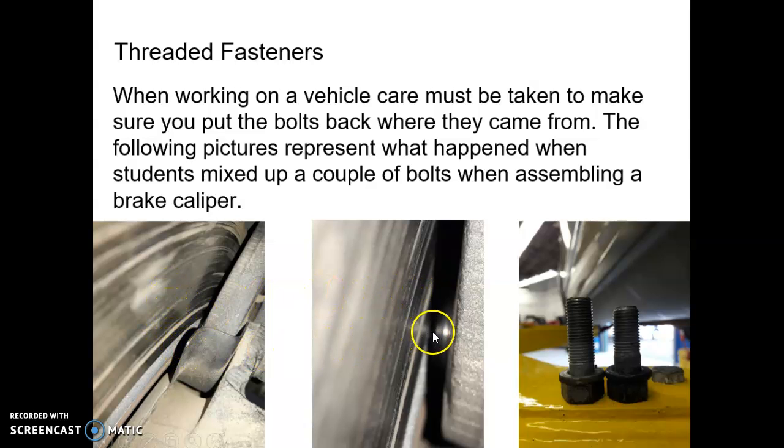The bolt was against the brake rotor and actually froze the wheel until we applied enough gas. It started to move, and it actually rubbed the bolt against the brake rotor enough to wear the brake rotor and the bolt. So it becomes very critical. A little difference in hardware can make a big difference in what happens after you service a vehicle. So you need to be careful and make sure that the right bolts go back exactly where you took them. This is one of the beginning technicians' biggest failures, not paying attention to what came from where.